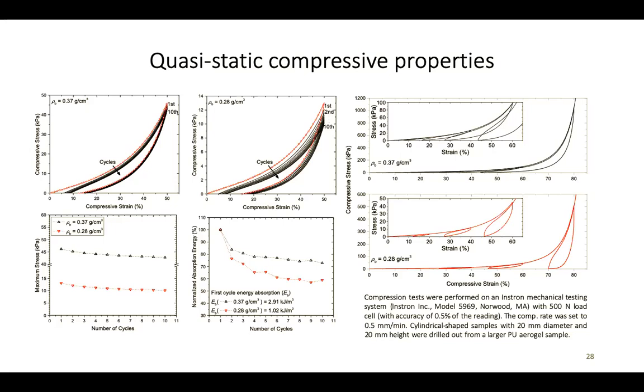In the second scenario, we load the sample and then we unload. As soon as the material is no longer following the platen, we start to reload it. So it's a load, unload, reload type of experiment, and you can see that the material has a shape memory property in itself. It can follow its previous stress state. This is the loading from the previous cycle, and this is the reloading from the next cycle, and you can see that the material can reach that state again.